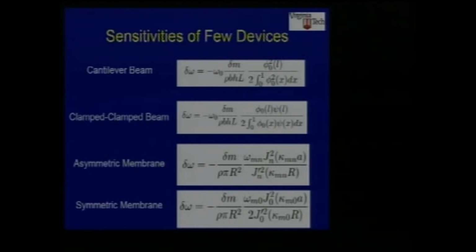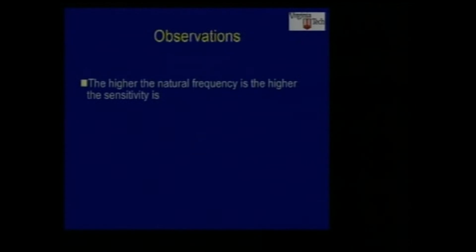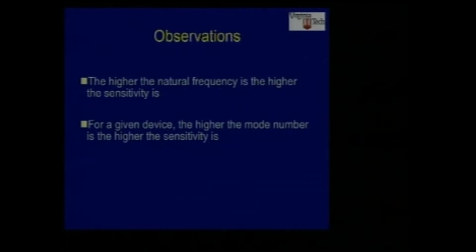to higher modes, you will get more sensitivity than if you go to the lower modes, because the higher modes have higher frequencies. These are the statements which I'm summarizing here. The higher the natural frequency is, the higher the sensitivity is. For a given device, the higher the mode number is, the higher the sensitivity.